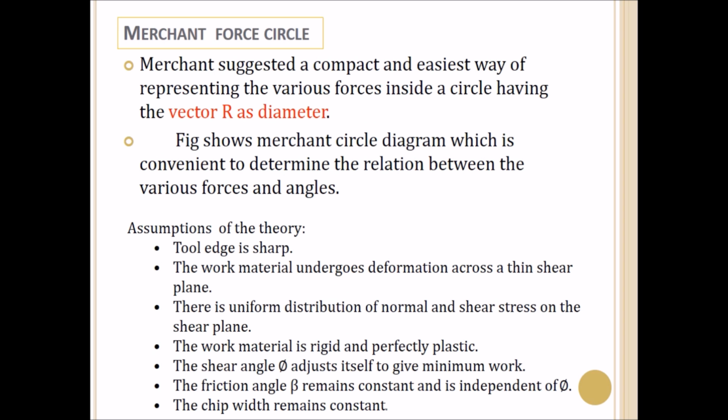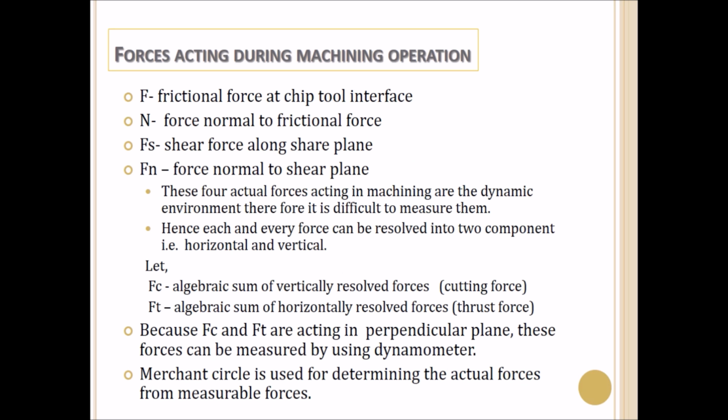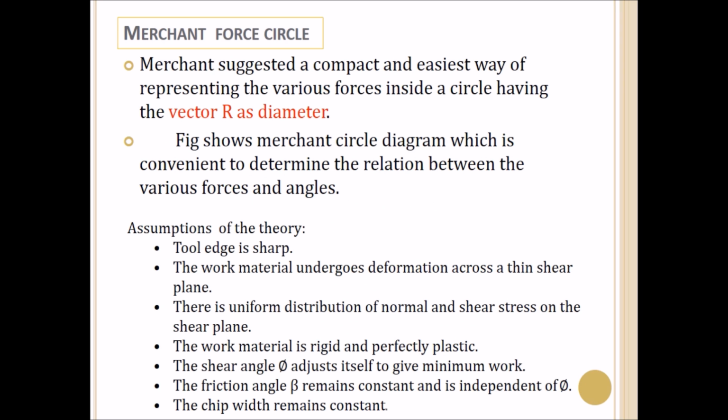So the Merchant force circle is a concept which can be used to find the various actual forces from the measurable forces, that is Fc and Ft, which we have just shown. Merchant suggests a compact and very easy way to calculate the forces actually generated in the machining operation. We are going to see the Merchant force circle in detail in the next slide.